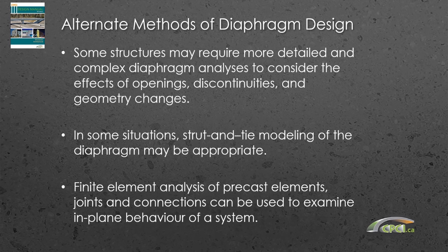And PCI has been publishing different papers, and there have been different research papers presented on how you can analyze diaphragms using finite element analysis, where you look at the stiffness even of the connections between the precast pieces and the overall diaphragm, and really need a proper structural engineering analysis of the diaphragm to get the load transfer. Basically, you're trying to take the loads from where they're applied and get them to the supports so they can get down into the foundation, and just following those loads properly through.